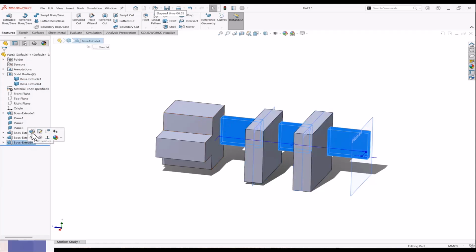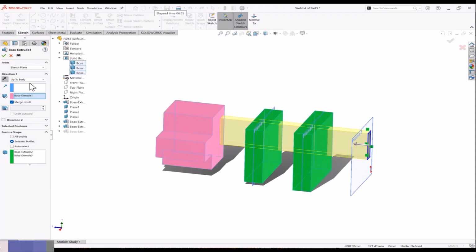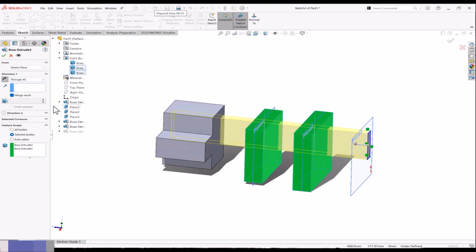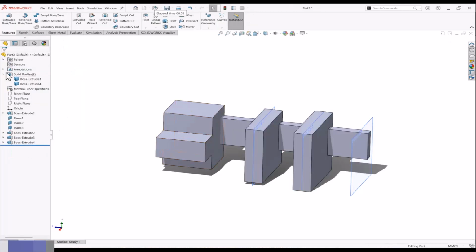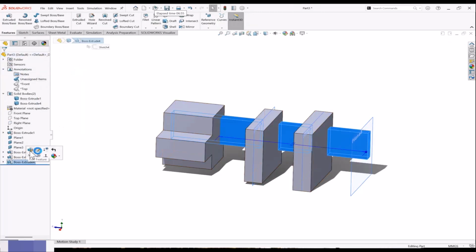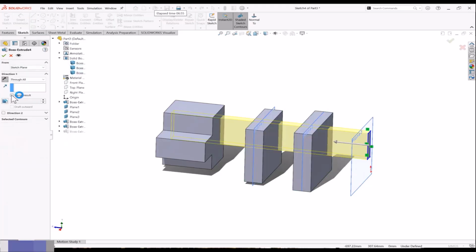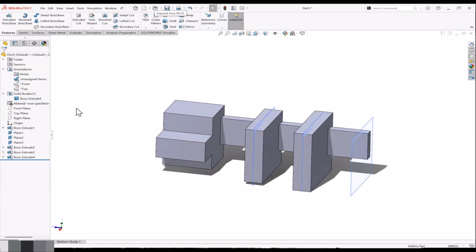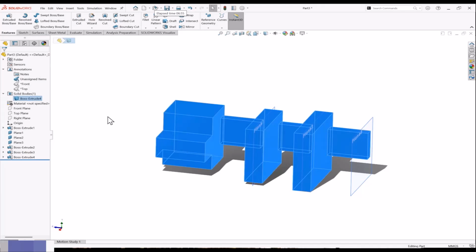But if I change the option in such a way, or any option I take, that it will pass through all or any other options. So we have a merge option there. It will be combined as a 1 part body. Okay, so you just have to check that option, unmerge it, take it again and do okay. And you will see it will get into 1 body.